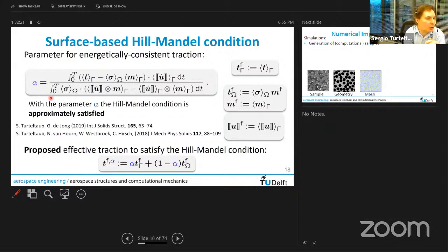And in fact, there are some limitations to this approach. To a certain extent, you need to have a certain separation of length scales for this to work to begin with. And what we have observed is that within the typical dimensions of plies, we can actually get at least effective properties for the ply in one sense.